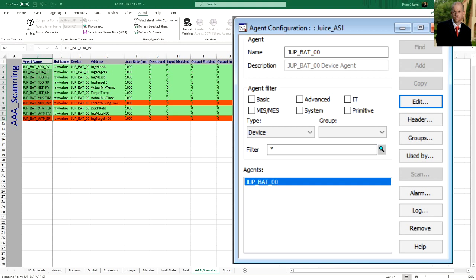Now, I expected this because this is actually a built-in error. Basically, what I've done here is put in the wrong addressing for our IO. OPC will validate its IO and will not allow us to scan an invalid IO tag, and we will then be returned. Obviously, if you get your scanning wrong on a Modbus device, or a Siemens device or a Mitsubishi device where those memory addresses are available, it will scan them in. So you will need to double check this, guys. It is very important.